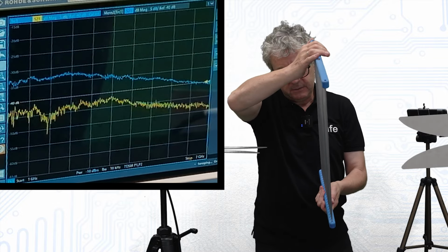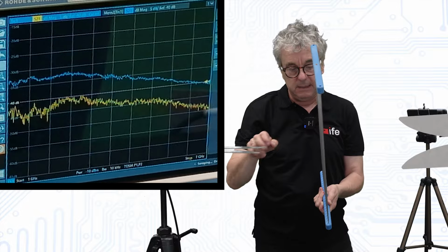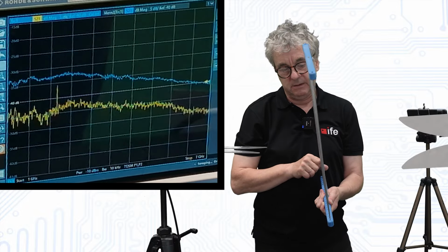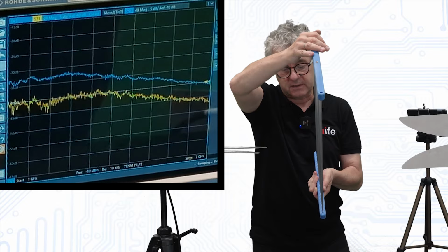This way, this 45 degree shield causes that part of the energy of the vertical polarization is transmitted in horizontal polarization, and this can be received. So now this antenna transmits here, but the initial field is not visible, but the reaction field is visible. And so at 45 degree, we get the strongest transmission, which is pretty much 6 dB down.